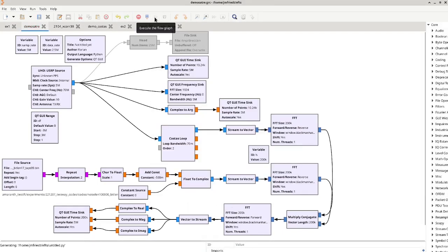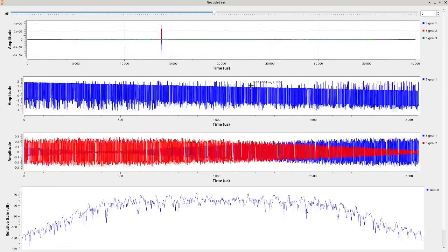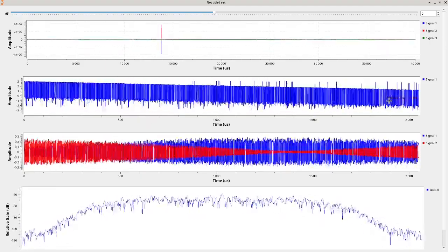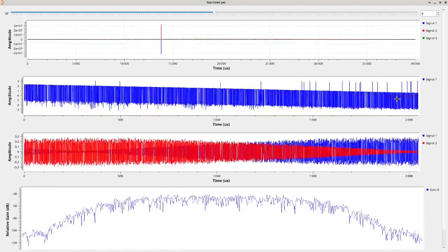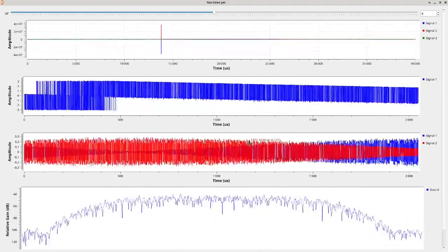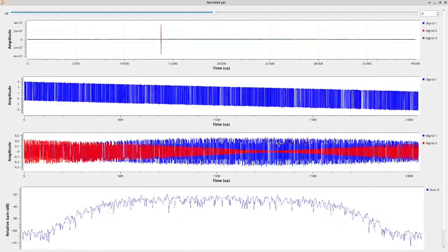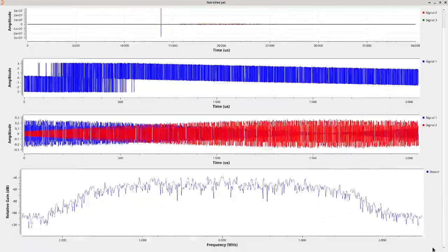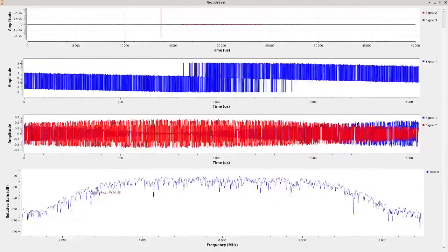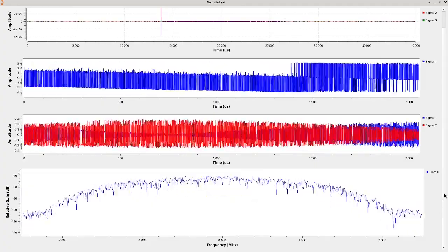meaning that the FPGA is run by one clock source and the B210 with another clock source, this time we will see that the phase exhibits a slope. The slope is the frequency offset between the transmitter and receiver. We see also this variation of the frequency as the beat note between I and Q coefficients. On the bottom is the 70 MHz intermediate frequency spectrum matching the requirements of the Telstar satellite.